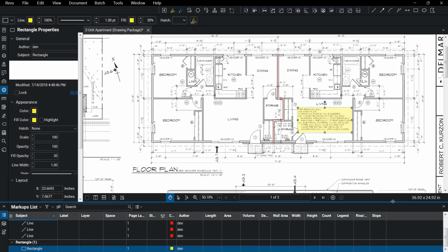Okay, the next question has to do with the dimensions, and what we do is we'll create the dimensions first, and then for your midterm you add those up and tell me how many lineal feet is in the firewall. So right now we're going to demonstrate how to do dimensions and then change the text of the dimension to black.